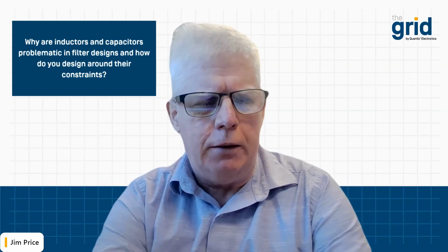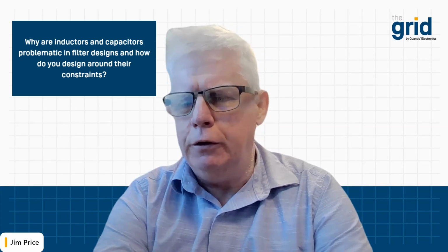Of course, maybe that's okay. It depends what your insertion loss requirements are and what your rejection requirements are. LC filters are used all the time, and they can adequately create good filters. It's just it depends on what your ultimate requirements are and your goals are. They are good for lower size and weight. They're very small and lightweight, so that is one advantage of LC filters. So I don't want to make them sound too bad, but they're generally not the first tool you go to when you need low insertion loss or high rejection.